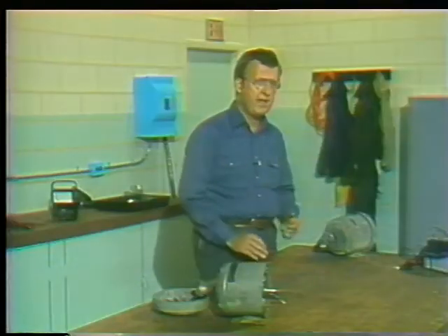If the ground is inside the motor and drying it doesn't help, the motor must be disassembled to find the problem. Now, when you've looked a motor over and you still can't seem to find a reason for a ground, then go to your supervisor. He'll decide what to do from there.